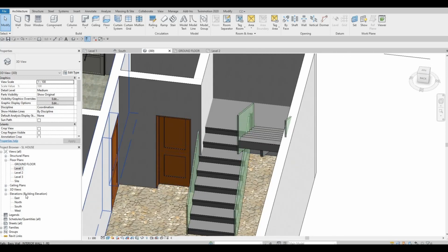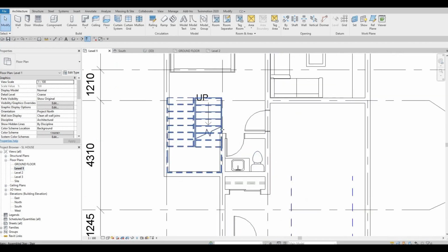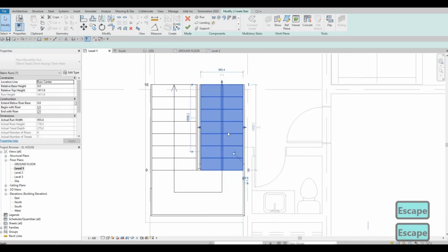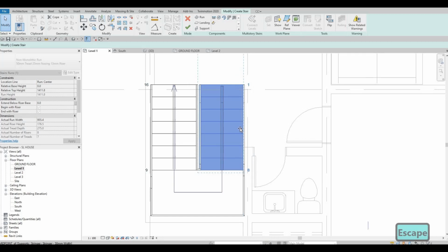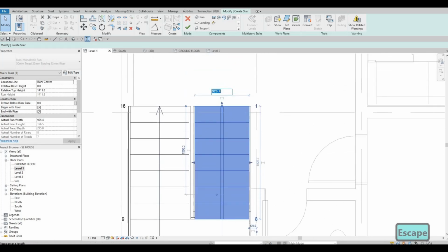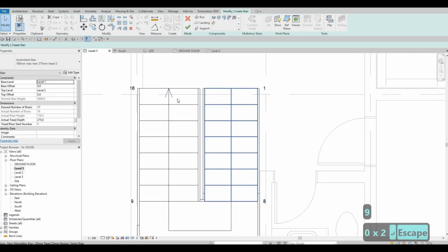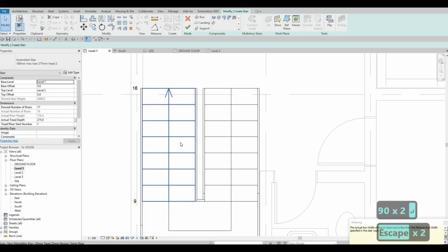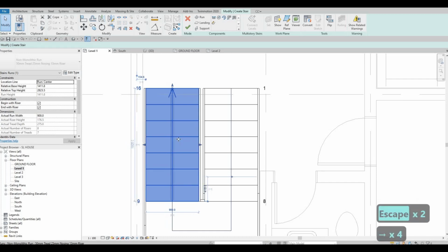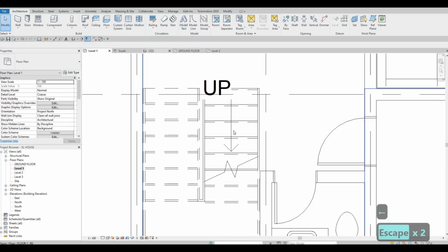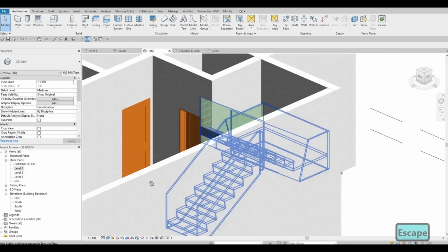And then at the same time, we need to go to right here, and then let's edit the stairs. I want to change the depth right here so that it's not actually going through the wall. So let's leave some gap. I'm just changing it up, maybe around 900, like that. And then here as well, maybe 900, and then let's move this one onto this side. Click on finish, and then let's look at it in 3D. So actually that looks much better.